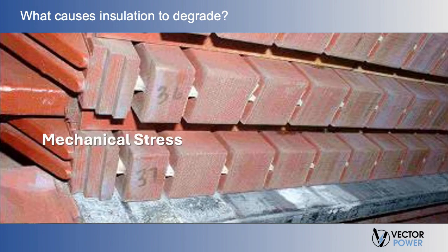Also, mechanical stress. Mechanical damage, such as hitting a cable while digging a trench, is fairly obvious, but mechanical stresses may also occur from running a machine out of balance or frequent starts and stops. The resulting vibration from machine operation may cause defects within the insulation.